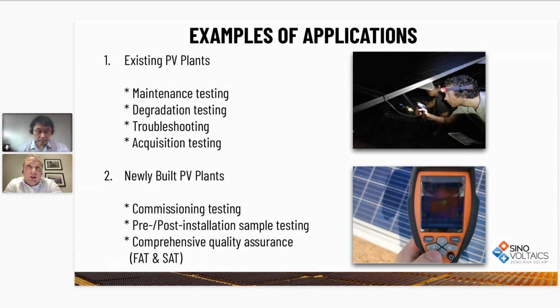So it used to be in the earlier days that people would walk into a power plant and do here and there some visual checks, connection checks, thermal imaging with a portable device. And then with the increasing popularity of EL imaging as a reliable quality control item, so to see what's going on at the cell level, the first portable EL testing kits also came out.